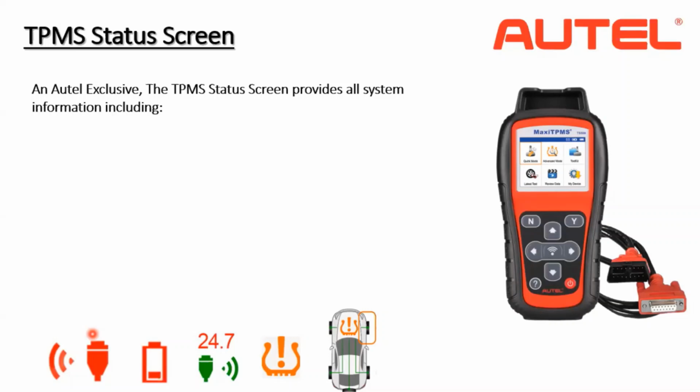Now, I will start with a general overview of the TPMS data screen, and then we'll show you how to utilize it during diagnostics. The information which we can get from the sensors and retrieve on the Autel TPMS tool are the pressure, temperature, battery life of the TPMS sensor, and malfunction indicator status, so you can know what is the actual problem with the TPMS system.